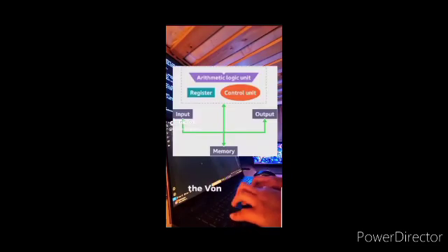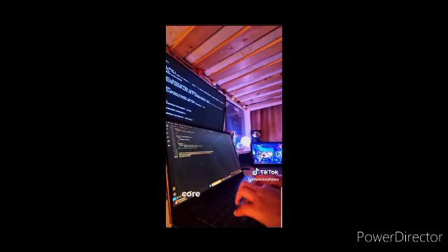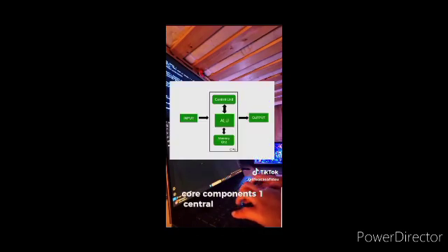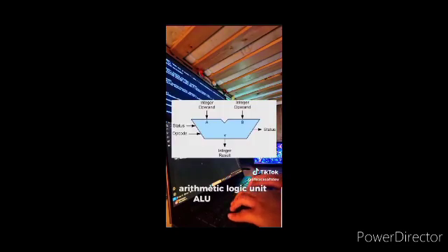of the program. The instruction register is a crucial component within the CPU that temporarily stores the instruction currently being executed. Here's a closer look at its role. Instruction decoding: once an instruction is fetched from memory and loaded into the IR, the CPU can decode it. This involves breaking down the instruction into its individual components, such as the opcode and the operands.